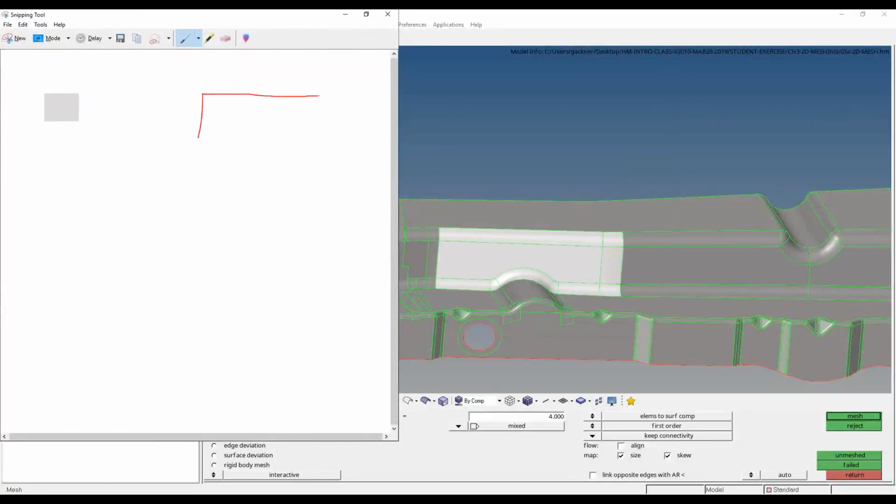In some situations where a surface is really getting tapered down to a smaller edge length, so maybe something like this trapezoid shape here, yes, I could include these taper lines in here to easily have 4 rows of elements, row 1, row 2, row 3, row 4. And if I do it with this approach, it's pretty easy to see how we can grid this up and have just square or rectangular-ish elements left behind.